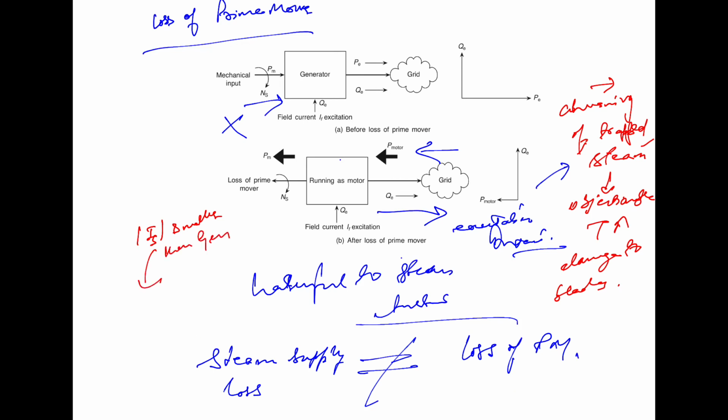However, it goes a phase shift of 180 degrees. Now, from this we conclude that if we use the directional relay with the maximum torque angle of 180 degrees using the phase angle conventions, then it would detect the loss of prime mover as the current phasor would reverse and enter the trip region.